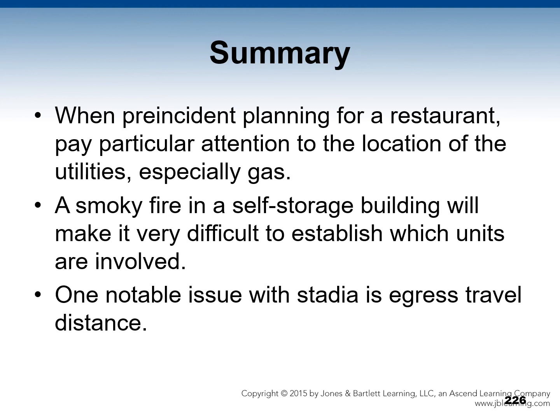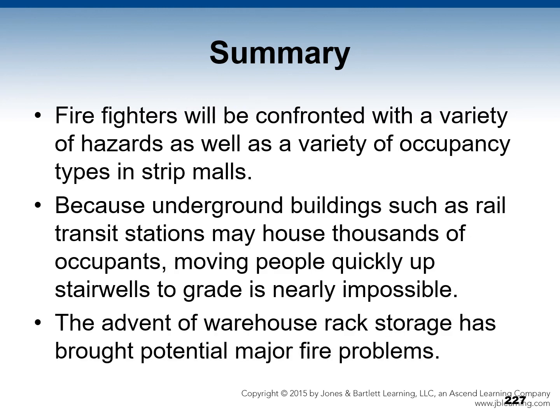In stadiums, one notable issue with stadia is egress travel distance. Most enclosed stadia cannot meet the traditional limits on travel distance from the most remote seat to an enclosed fire-rated stairwell. In strip malls, firefighters will be confronted with a variety of hazards as well as a variety of occupancy types.